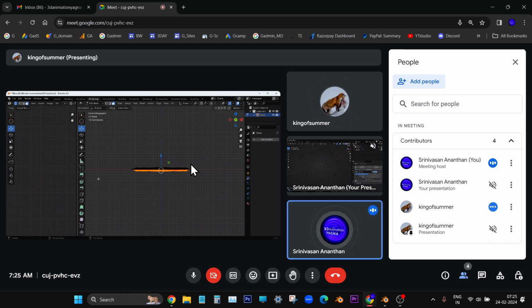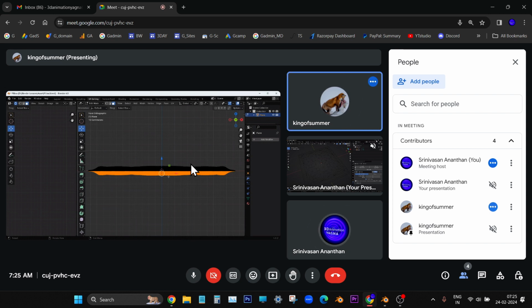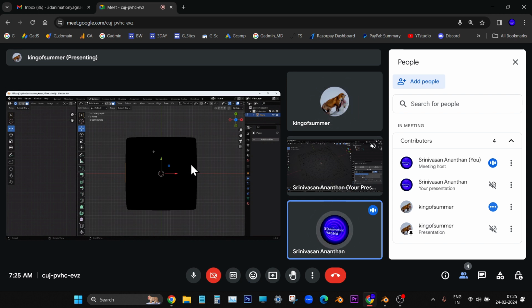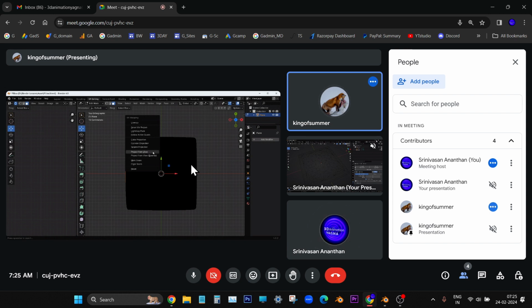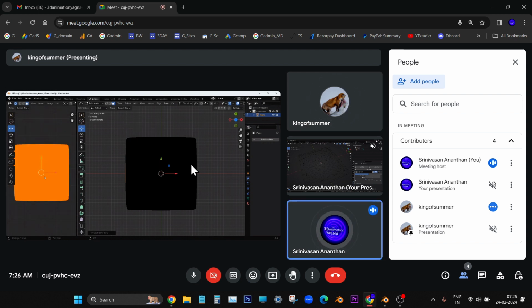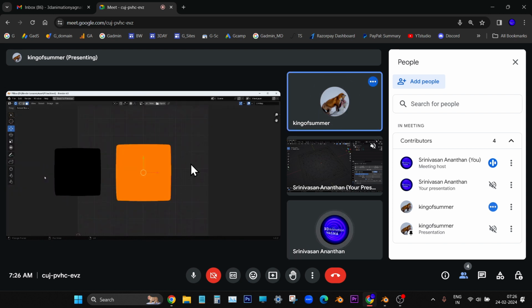Right. Now we have to press U. Go to top view, don't deselect anything. Press 7. Now press U on the keyboard. Project from View. Yeah. Now press Ctrl Space. Do you see two things?